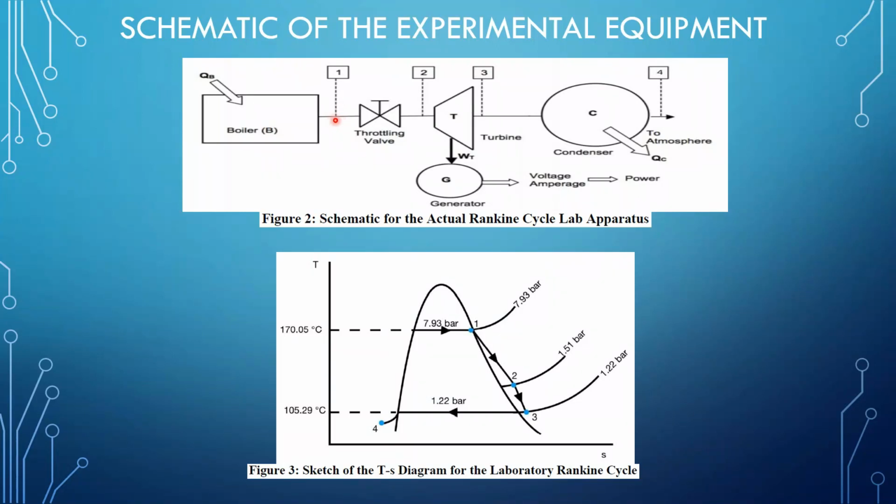Now to bring it to the superheated condition, we have this manual throttling valve or the steam admission valve. And by throttling the steam from 1 to 2, that reduces the pressure of the steam while bringing it to the superheated condition. So the steam at 2, which is the steam entering the turbine at the turbine inlet, this steam is superheated, right, at a lower pressure than at 1. Right? Now this steam enters the turbine inlet, right, and produces mechanical work.